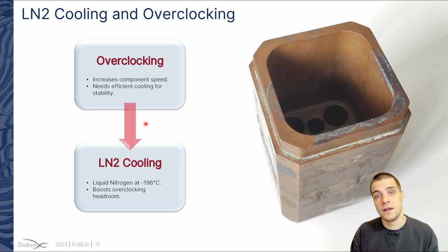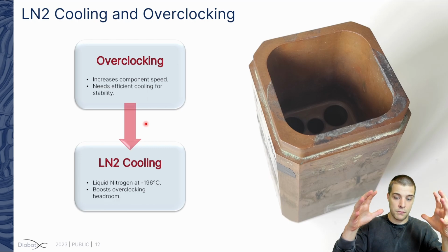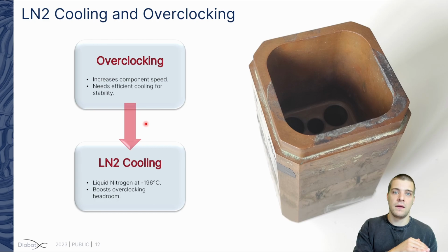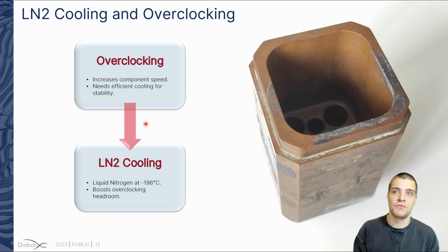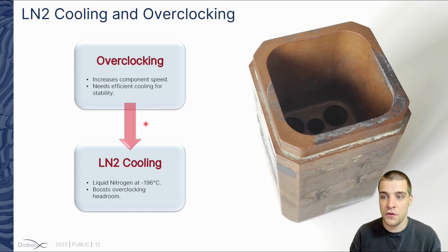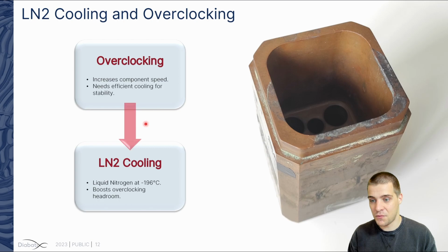And by using the boiling principle, you're basically stuck at that temperature. So with boiling, you basically start from fully liquid, and the temperature is fixed until everything is evaporated. And by using this, you can basically dramatically increase the heat transfer coefficient of your cooling solution. I hope that's all clear.